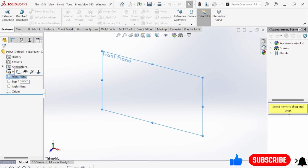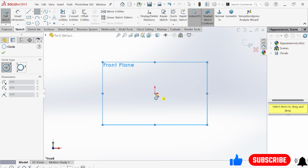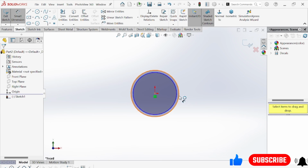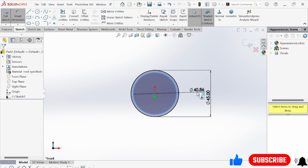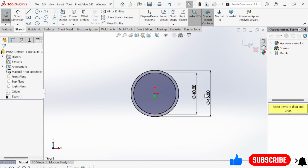We will start with one plane, which is the front plane. We have to make half of the circle. How? Just make two circles like this, and let's define their dimensions. Let's make this one 45, and this one will be 40, because we need a 5 thickness of this material.